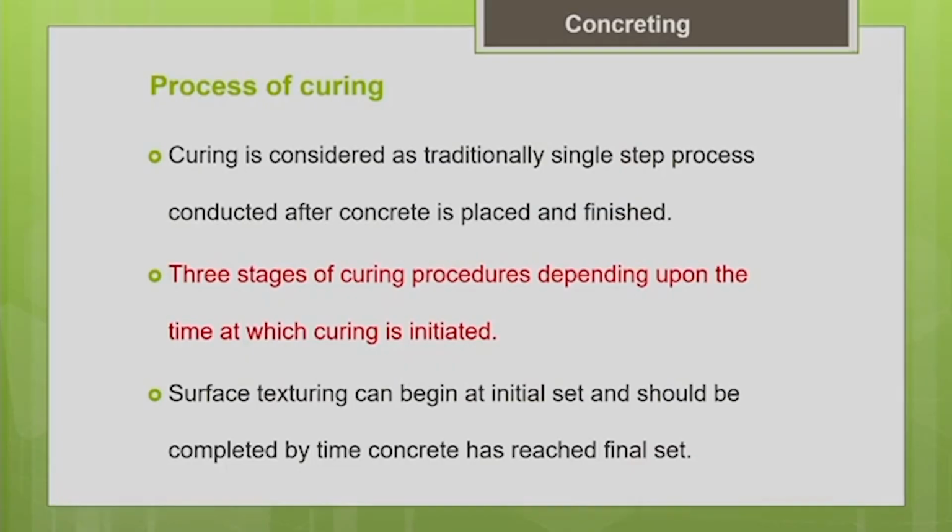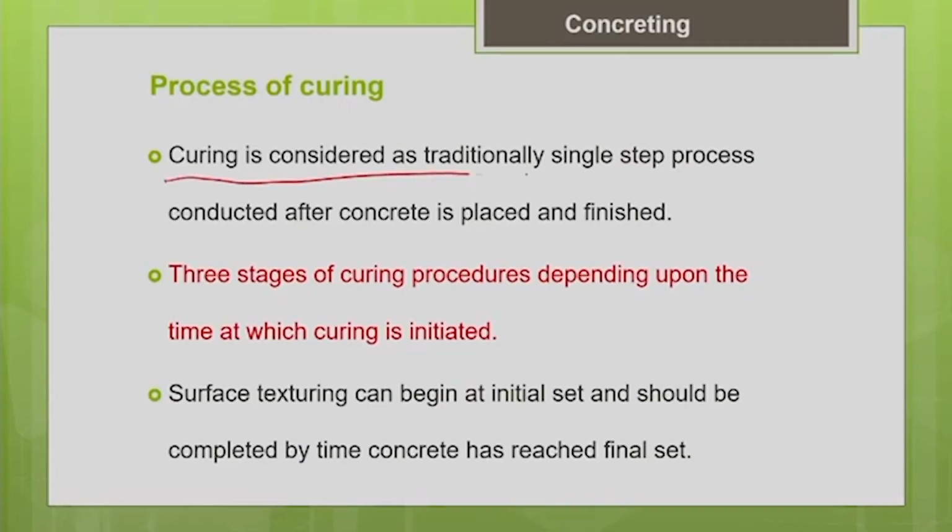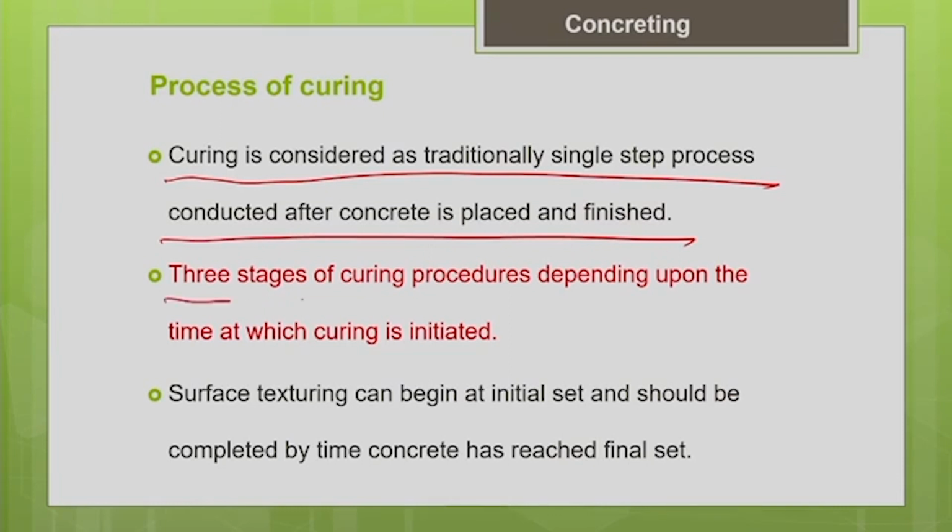So, basically earlier curing was done in only one step. Mostly after the finishing of the concrete, curing is done, but now we do the curing in stages. Curing is traditionally considered a single step process conducted after the concrete is placed and finished. But nowadays we do it in stages, as I told you, there are 3 stages of curing depending upon the time at which the curing is initiated.